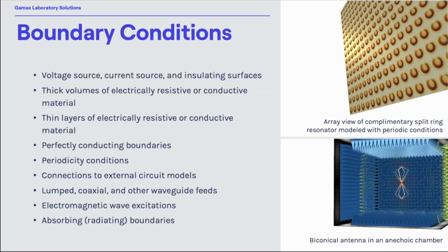And boundary conditions: there is a very, very long list of boundary conditions available for different purposes, but with the perfect electric conductor and some lumped port and excitation, technically in most cases you can start to build your very first antenna. And then you can extend with more, like including external circuit layouts.